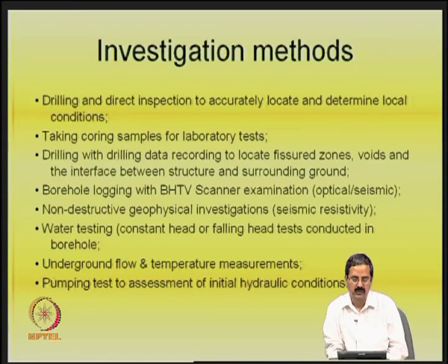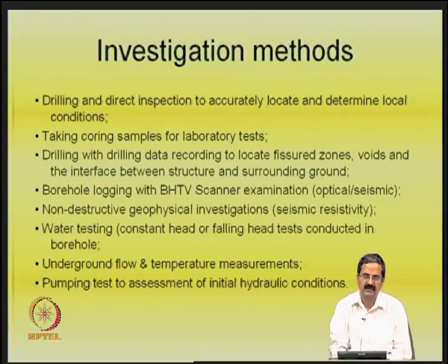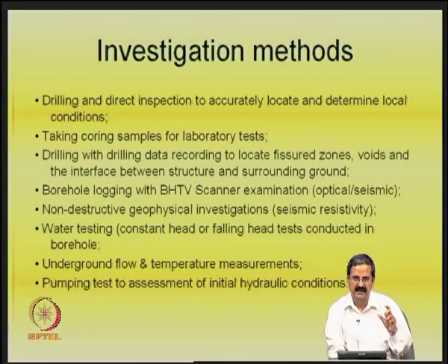Particularly, you can find out the permeability of the rock or soil, because the objective is essentially to find out the pore size here. If the pore size is bigger, you would like to see what its impact is and how to use the proper grouting method. So, the permeability is quite important.